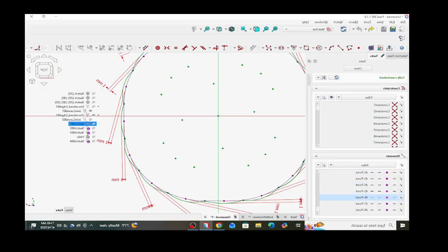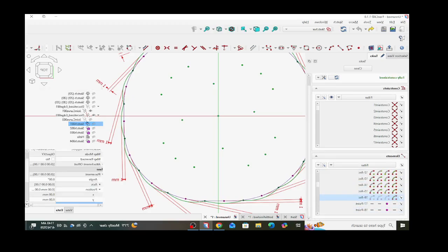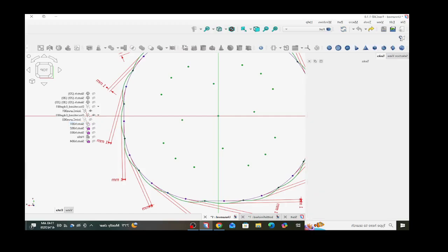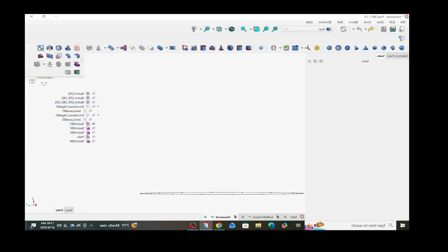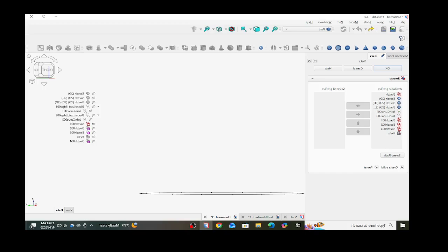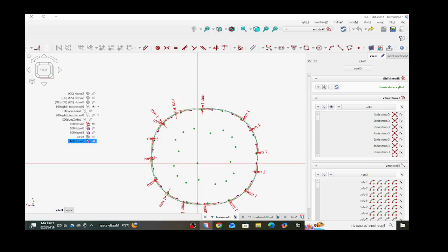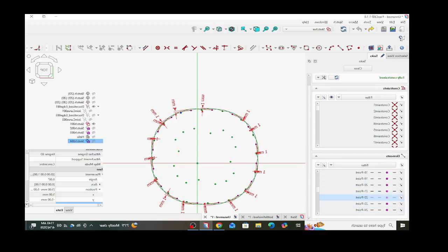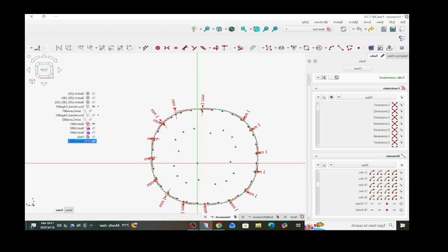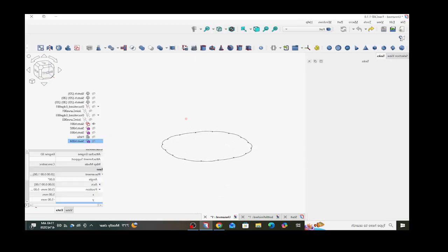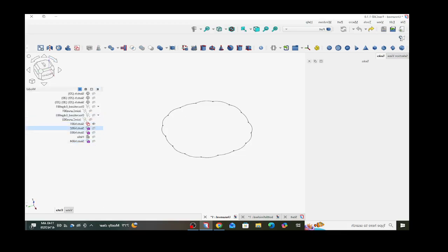Okay. You gotta select all these points. Hold down Shift and select them. Make them construction geometry. Now we'll go back into our sweep and sketch 001 is there. Sketch 004 is not though, so we need to do the same thing with it. Scroll down, find all these points, select the bottom one, hold down Shift and select the top one, then click to make them construction geometry. Hit close. Alright, we're good.